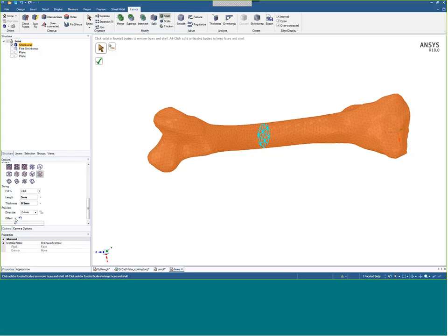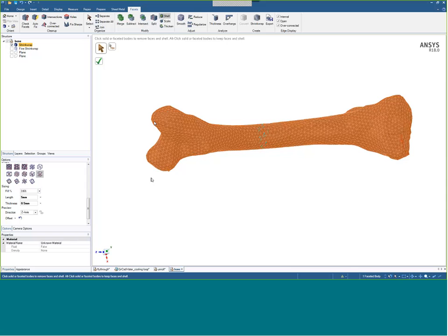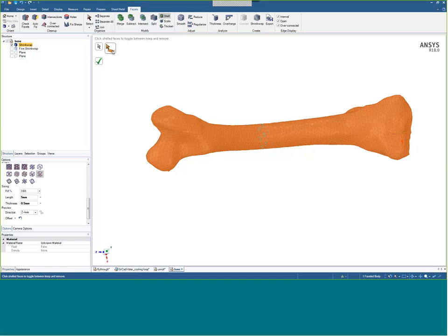One thing I think is really helpful with this as well is that you can actually see the offset going through, so you can see what that might look like in various cross-sections. And normally this would be a lot finer. We would have a lot more facets. I'm making this fairly coarse just to show you what this would look like. But one of the other things I wanted to add with this as we're going through is the ability for you to see the inside of this. So instead of just making an infill in this solid part, I'm actually going to shell and remove faces from this model. So here we'll remove faces from the design. I'll remove some of the interior, and we're going to go ahead and create this.